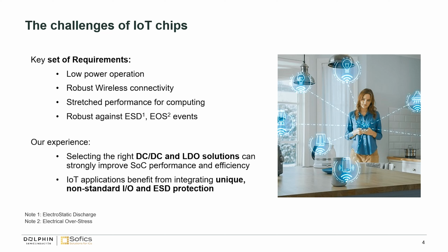Our experience that we bring here, Dolphin Semiconductor and Sofix, is first selecting the right DC to DC and LDO solution for a low power device and a wireless device. You know that DC to DC can generate a lot of noise that can disturb the radio or any ADC analog converters. And here we have a pretty good solution, and there are some real points to take care about.